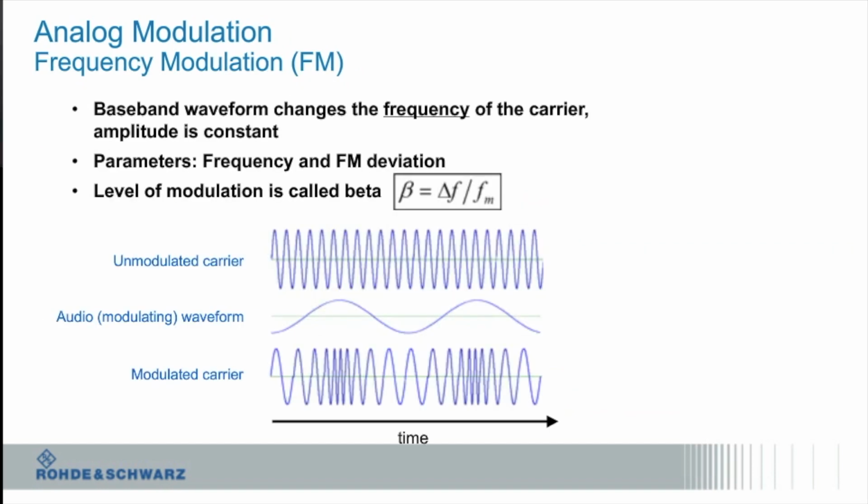Okay? So that was amplitude modulation. So now we're talking frequency modulation. Take that same carrier, same information signal, and now instead of changing the amplitude of the carrier, I'm changing the frequency. So you see here, as the amplitude increases, the frequency gets faster. So the information is on the change in the frequency.